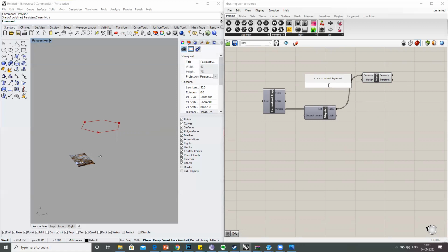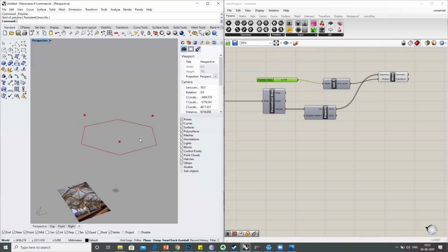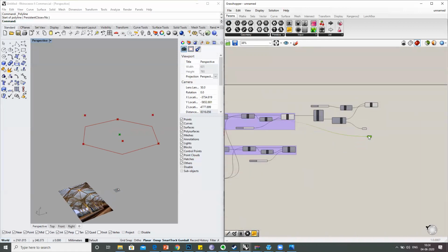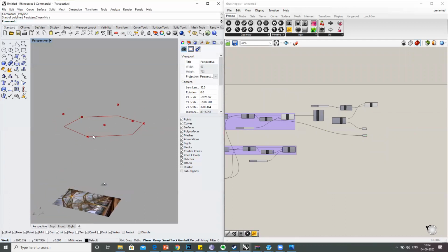So you're moving those 3 points in the Z axis to a height of, say, we can have a maximum of 1 meter. So I can do a 1 lesser than 1000. If you see, this is going to give you that alternation. Now, these are the first set of points. Now we've got a second set of points, these are the second set of points. And then we've got a midpoint from the area centroid. So this will get me my midpoint.